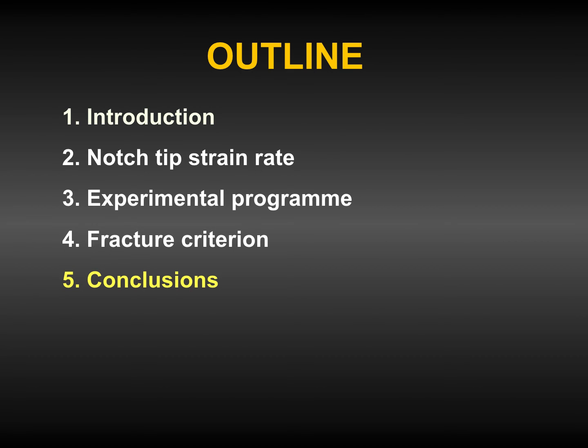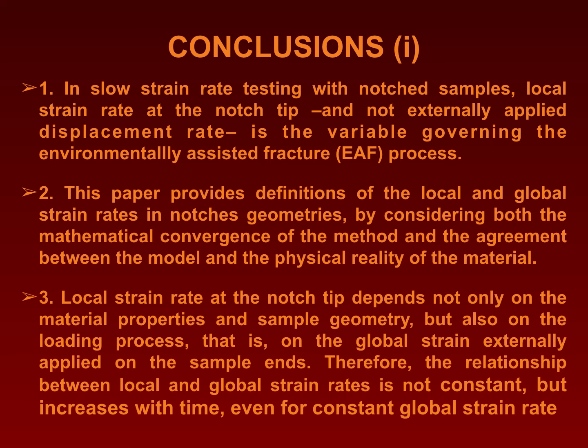Let's go to the conclusions. 1. In slow strain rate testing with notched samples, local strain rate at the notch tip, and not the externally applied displacement rate, is the variable governing the environmentally assisted fracture, EAF, process. Second, this paper provides definitions of the local and global strain rates in notched geometries by considering both the mathematical convergence of the method and the agreement between the model and the physical reality of the material.